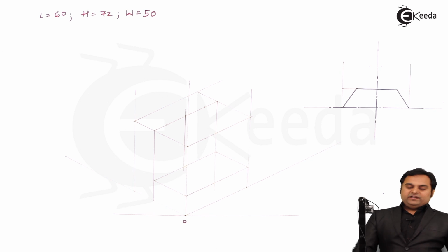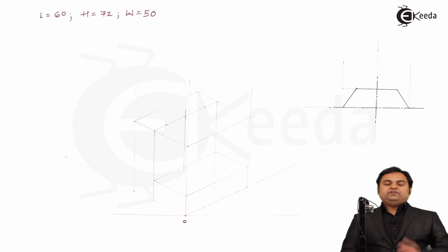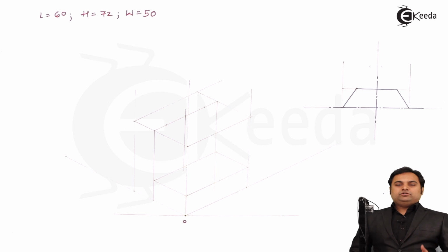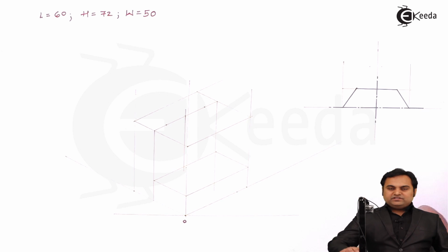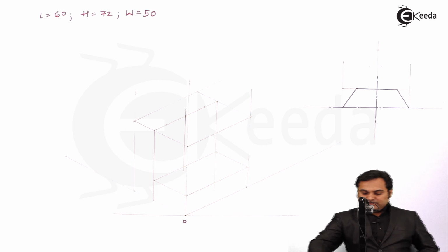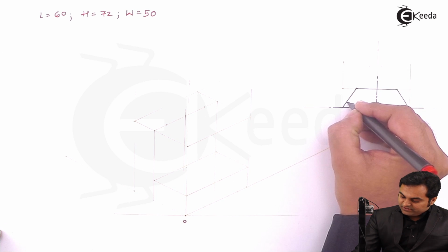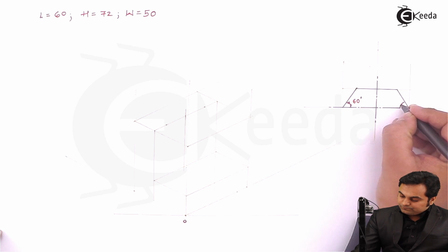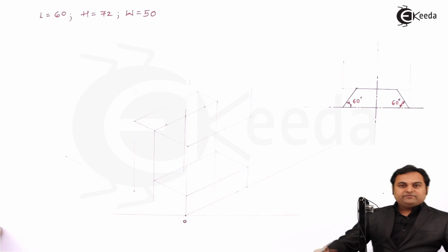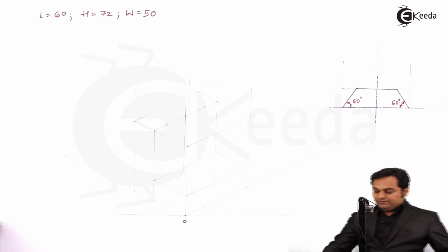So if we measure any angle over these lines, we are going to get a value more than 30, because 30 will already be added. So it is better to draw any given surface which is at a particular angle. In this case the surfaces are inclined at 60 degrees. So it would be better to draw them separately and then copy them onto the diagram itself.